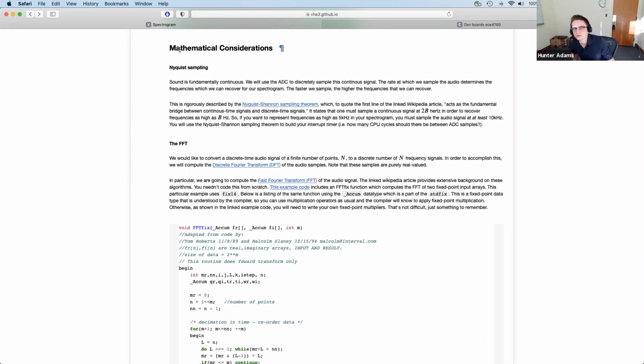So what are the implications of this as far as lab 3 goes? When you move that slider, you're going to be changing the effective range of the spectrogram. You're going to be doing your analog to digital converter sampling within an interrupt service routine, because just like when you were producing sound, when we're listening to sound, precise timing is important.